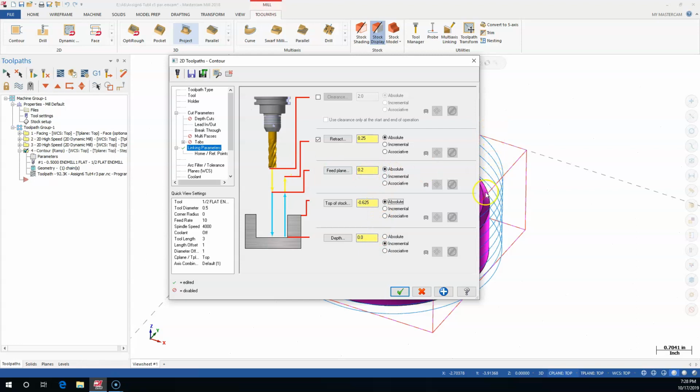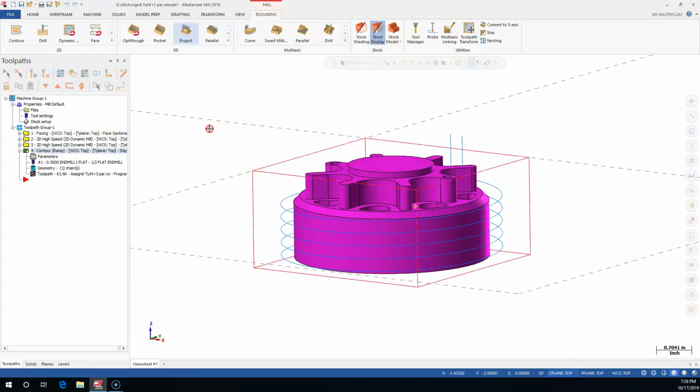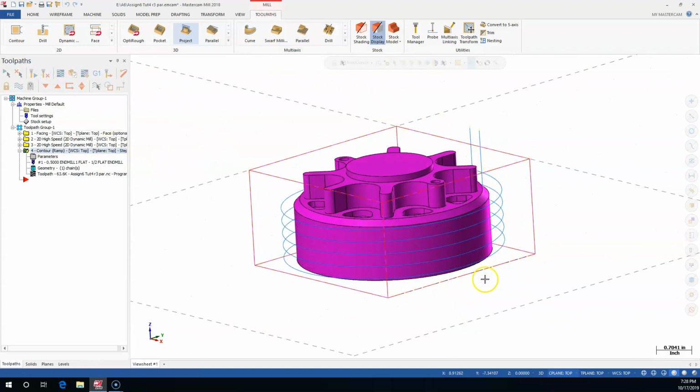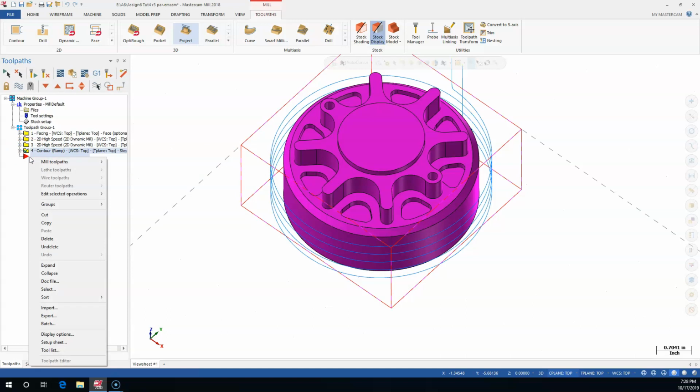And even if it feeds in slow linear, I can always switch the feed plane over to incremental so that it picks up that first step, or change it to, maybe minus 525, whatever we need there. Okay, one more regenerate. All right, so I have the feed down, it starts the ramp, we take the cut, and then we should be ready to set our finish passes with the 1/2 inch tool.